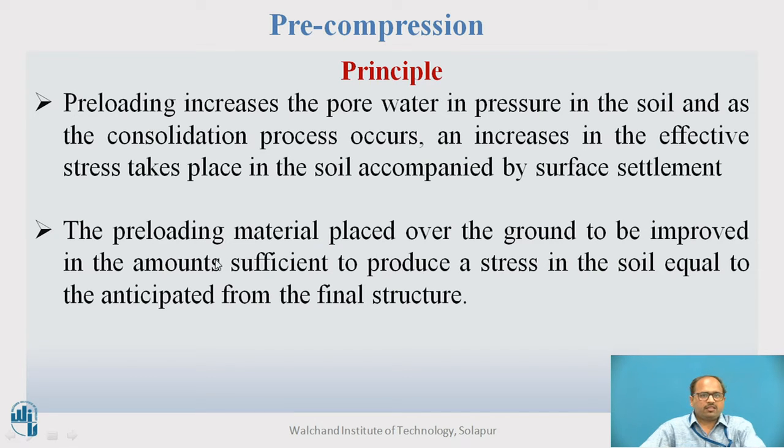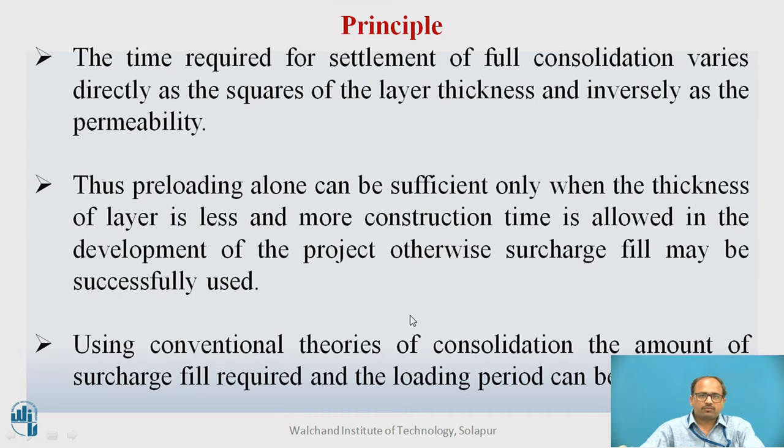Then, the preloading material is placed over the ground to be improved in amounts sufficient to produce stresses in the soil equal to those anticipated from the final structure. This preload will be equal to your final structure load. The time required for full consolidation settlement varies directly as the square of the layer thickness and inversely as the permeability. Your settlement depends on your consolidation process.